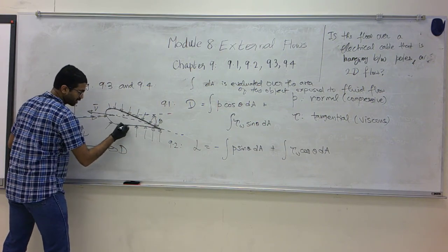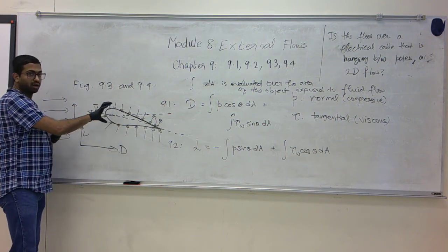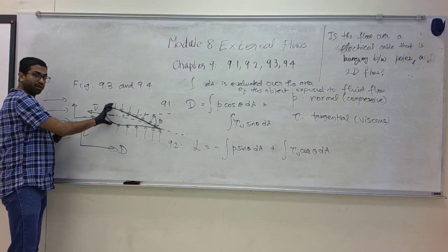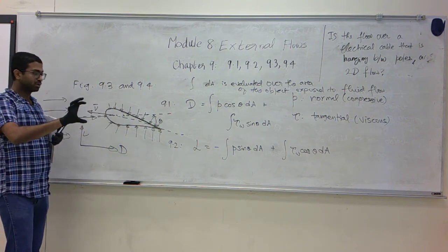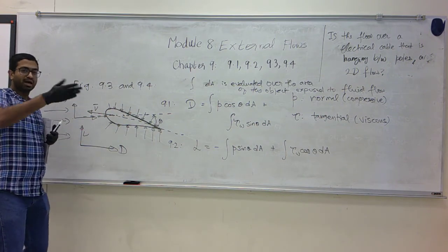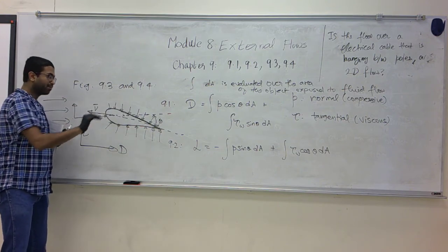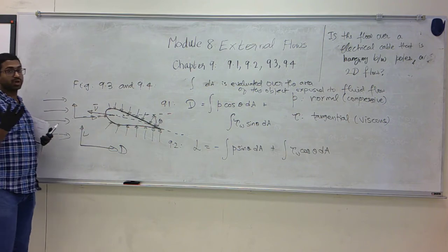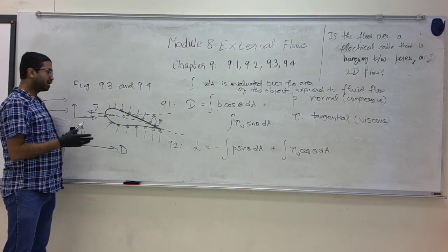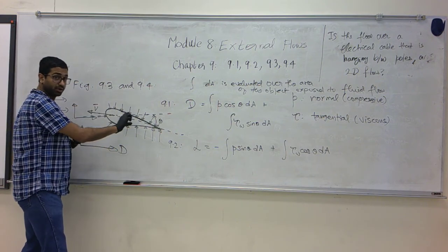This is a cross section, remember. If you want the area, you should understand what is called the span width. That is, if this airfoil extends, let's say, 1 foot or 100 foot or 10 foot in this direction, it's the area over which the fluid flows. So if this were a very long airfoil, a wing, and you are calculating the drag and lift near the middle of the wing, you would just consider this to be a 2D flow.